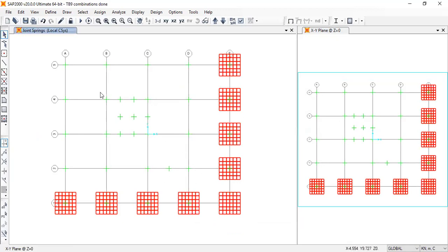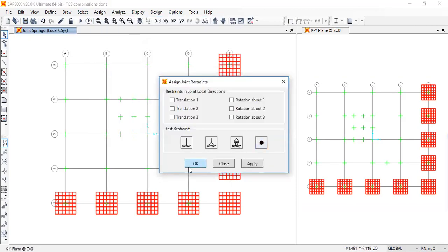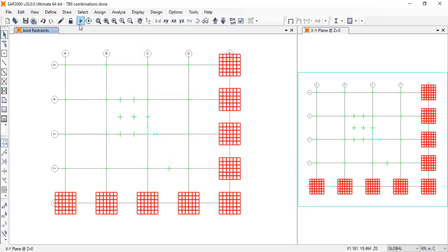For something like this, you have a combined pile cap, right? You have seen in the lift area, there's a huge lift core, right? So the entire area is a large pile cap. So something like that, you can do it. When you analyze it, you need to get rid of these supports. The structure is still not stable; I'll show you why next week. Joints, restraints, I don't have any supports here, so it's safe to analyze.